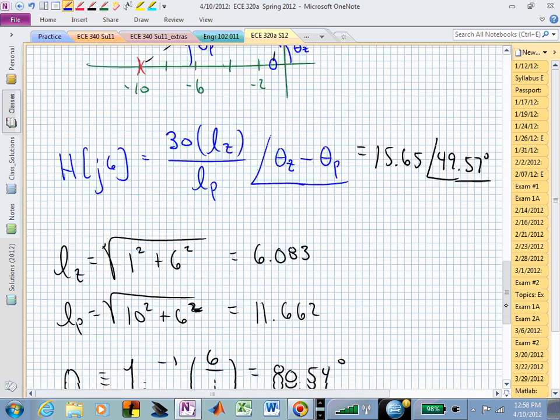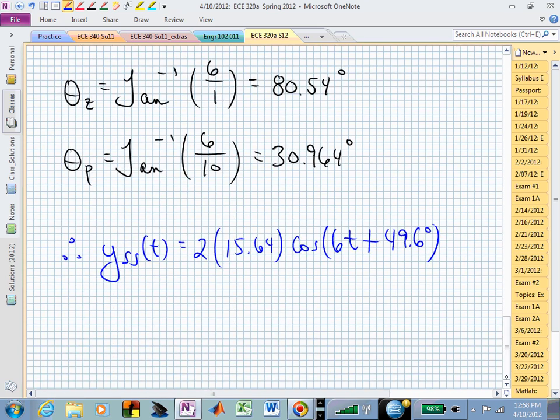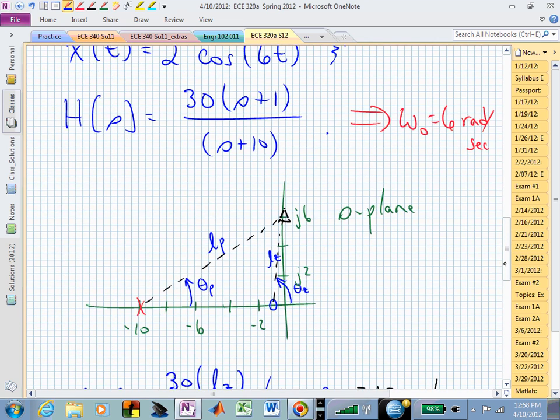Let's start talking Bode plots. Now what we want to do is, instead of doing this point for point, see that triangle? We could theoretically march that triangle from 0. If we evaluated this at 0, that would be our DC gain. If we go up here, then it's j0.1, j0.2, j1, j2, etc. If we did that for all of the points on the imaginary axis, that's the information we want for our frequency response. That tells us how this particular system responds to any given signal.